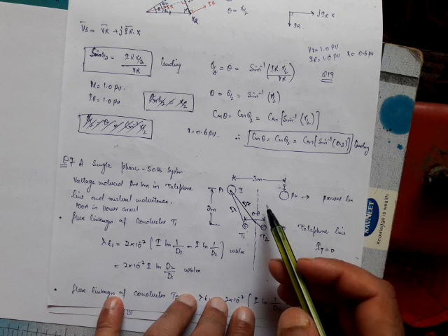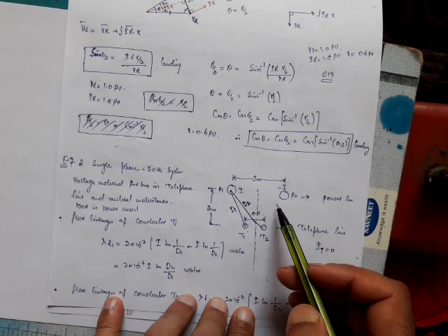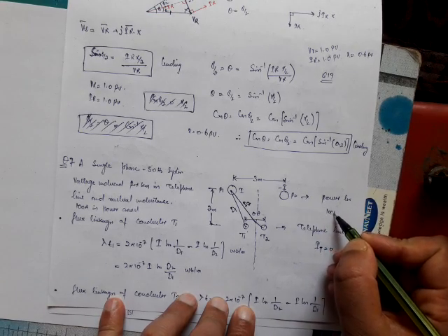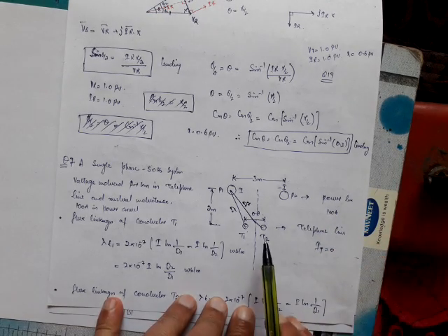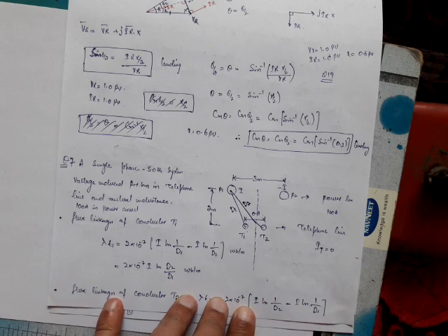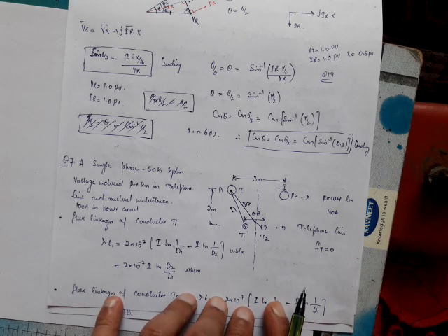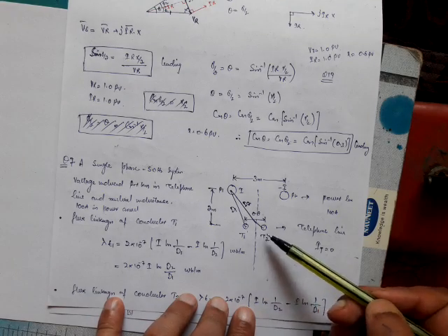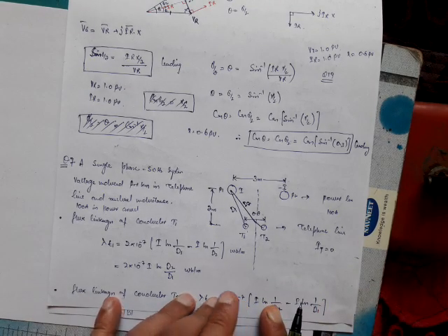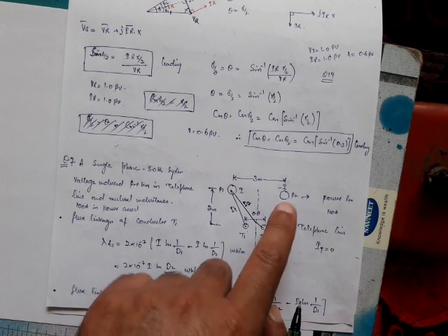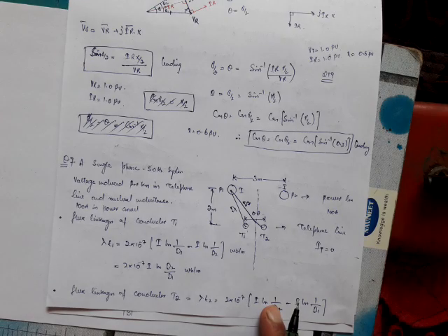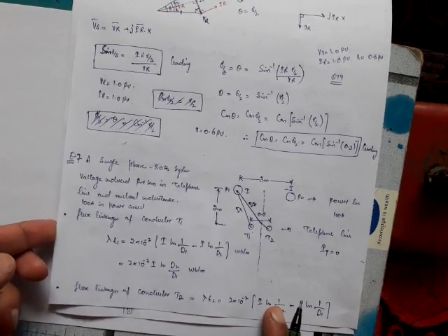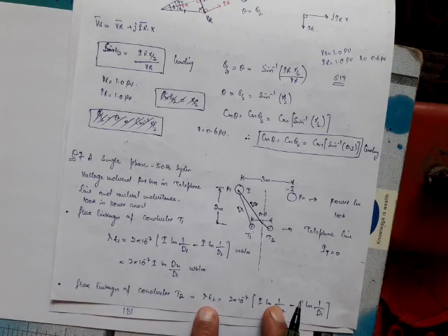And the power line is carrying a current of 100 amperes, and assuming that the current flowing through T1 and T2 is 0, we need to calculate the flux linkages due to these conductors in T1 and T2, that is the telephone lines. And due to these flux linkages and the current flowing, we need to calculate the voltage in the telephone lines. What will be the voltage induced?